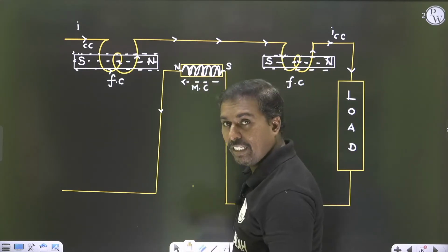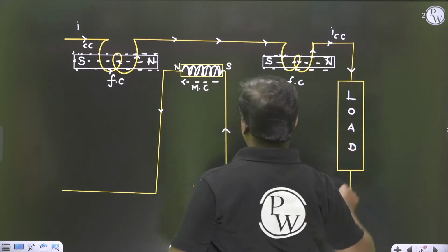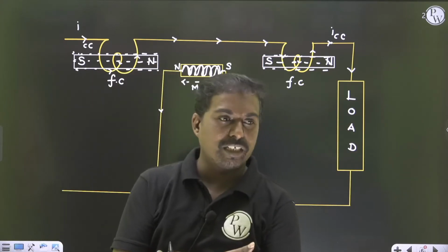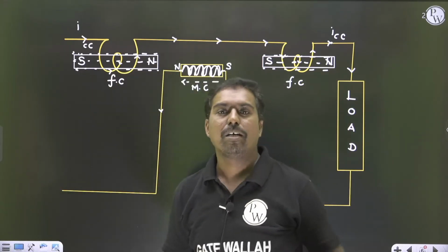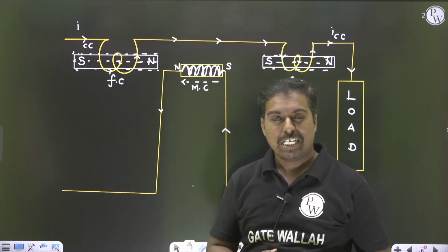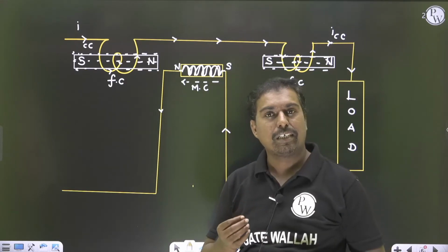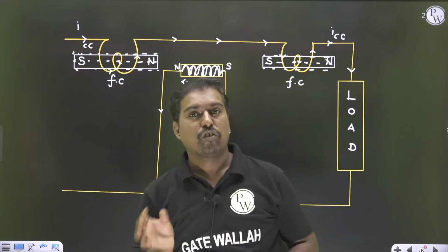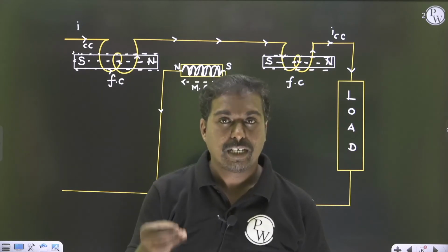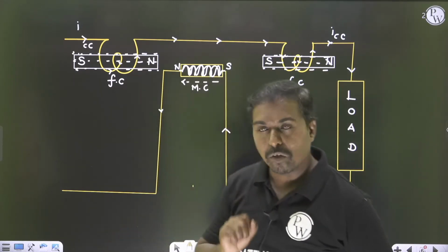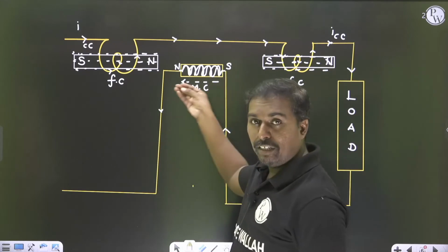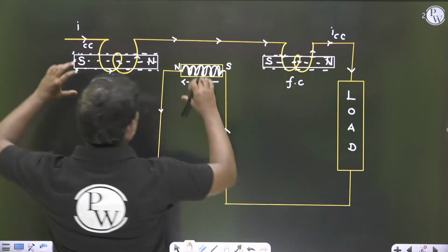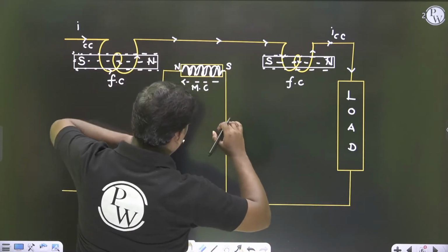The reason behind it is when the same series current travels here, but the direction is opposite. So another magnetic field is going to be created in that moving coil, because they are all electromagnetic coils. So that is the advantage of this particular dynamometer instrument. In dynamometer instruments, we are having 3 coils, but the 3 coils are lightweight because they are air cored coils. So these air cored coils will have certain magnetic flux opposite to each other, which is having a reverse magnetic field, which makes this particular moving coil deflect.